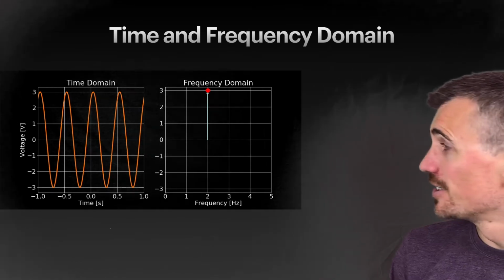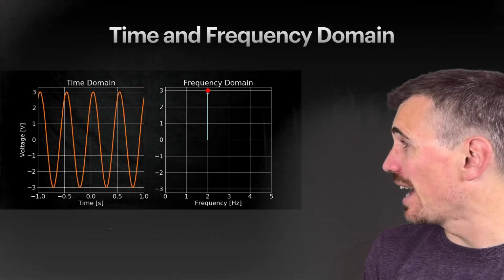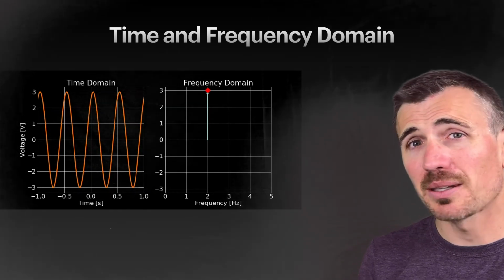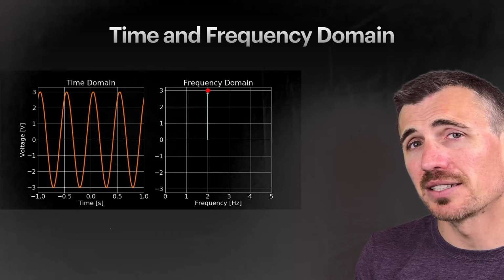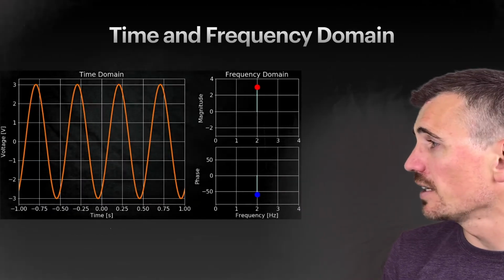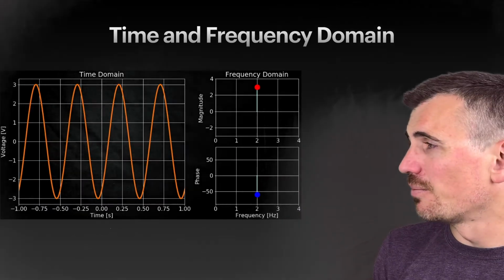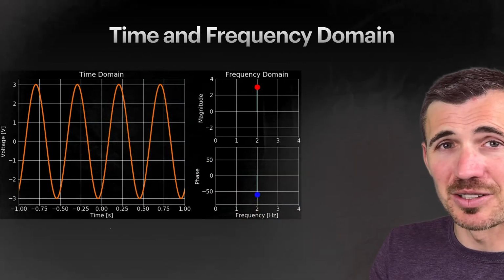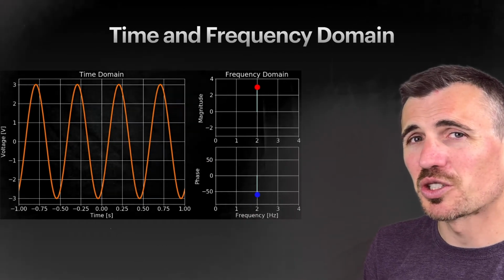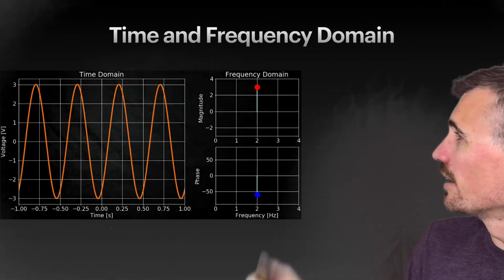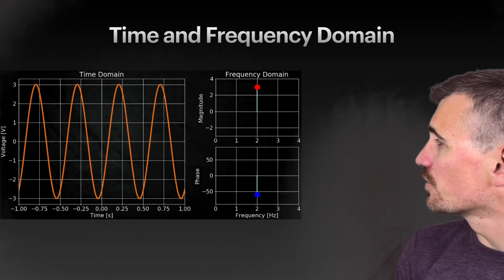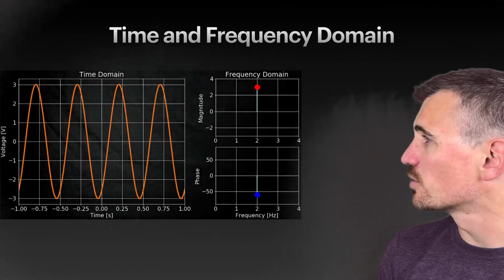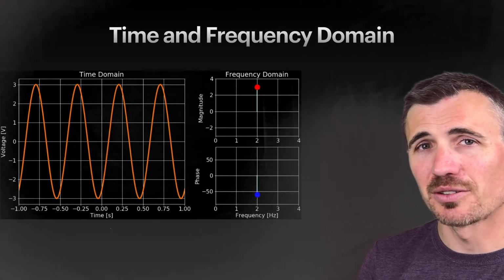So in this case, we're only plotting the amplitude at that frequency. We might also want to know the phase. Not always. Sometimes we just want to know what the RMS of that signal is. But then we can write either a three-dimensional plot with frequency down one axis, magnitude and phase. That looks very fancy, but it's often more useful just to write it as two-dimensional plots where we're looking at the phase versus frequency and the amplitude versus frequency. And that's what we've done here. So this whole thing is represented by these two numbers at those frequencies.